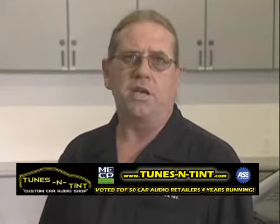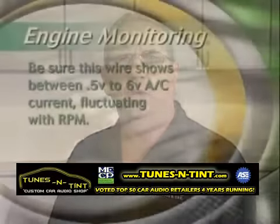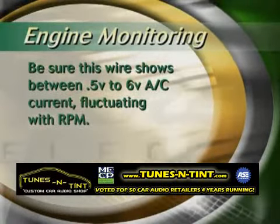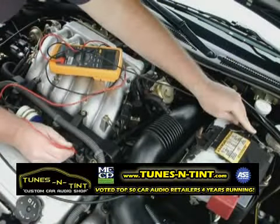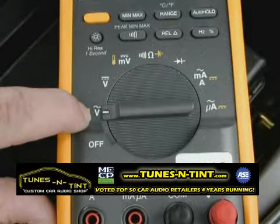Directed recommends using a fuel injector wire or ignition coil to make this connection. You may also use the wire listed on your vehicle-specific wiring diagram. Be sure to properly test this wire and confirm that it shows between 0.5 volt to 6 volts AC current, fluctuating with the RPM. To do this, put your red probe on the suspected wire, your black probe on ground, and set your meter to measure AC voltage. It is recommended that you solder this connection.